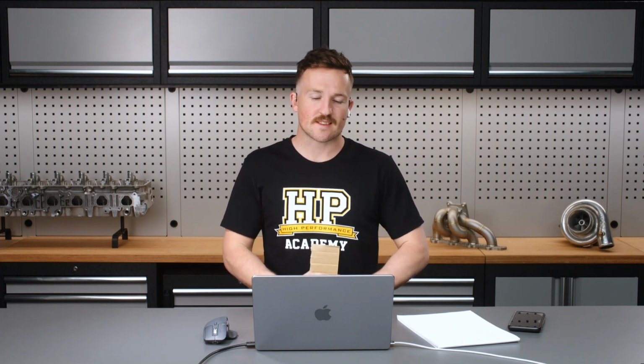Sometimes if we bend a part in Fusion 360, that's all good and well, and then we go to our sheet metal folder on our workbench, or maybe we're using a vise or something like that, and we just can't create the bends how they were in Fusion 360. One of those things comes back to our sheet metal rules, and that is if we're using a special press to bend our part where we have dies and that will control the radius of the bend, that's all good and well, and those sheet metal rules are great for controlling that and making sure that we've got it correct.